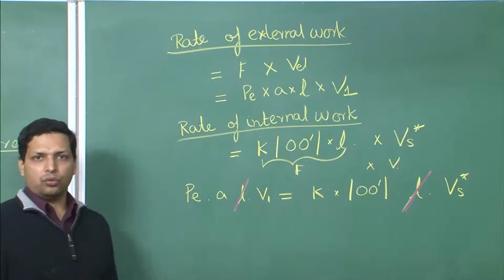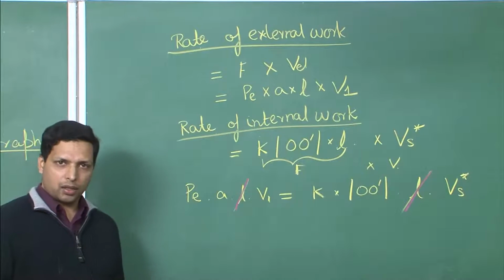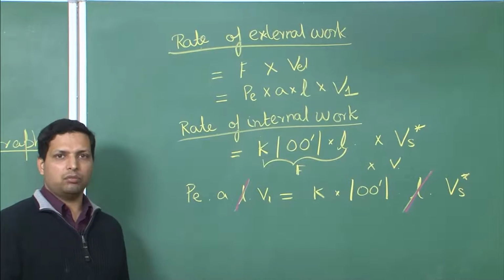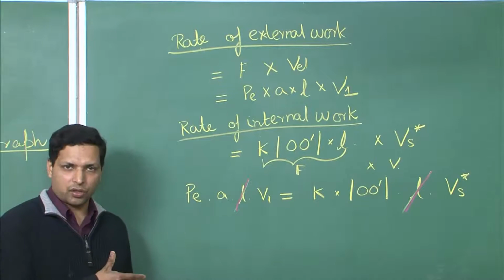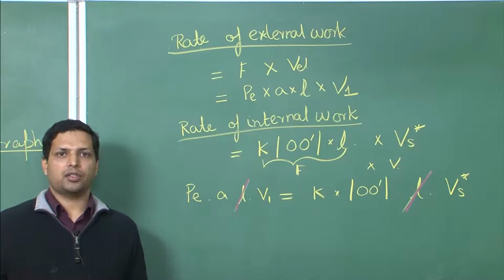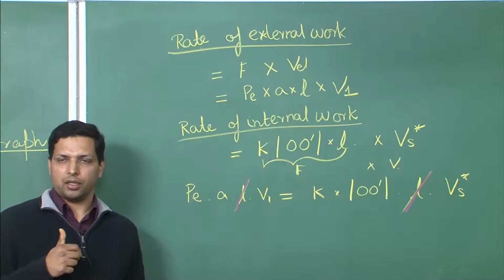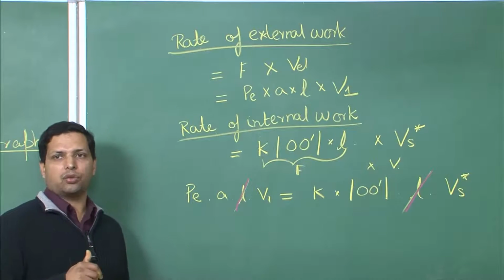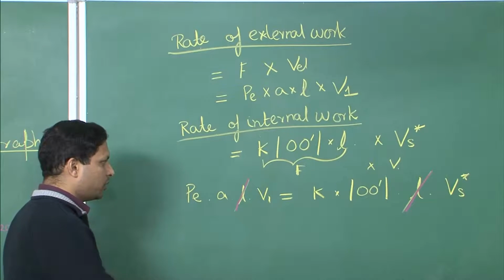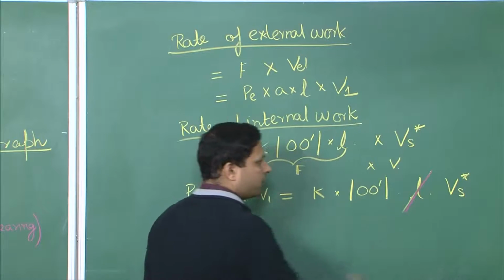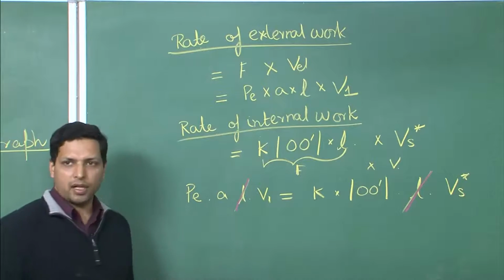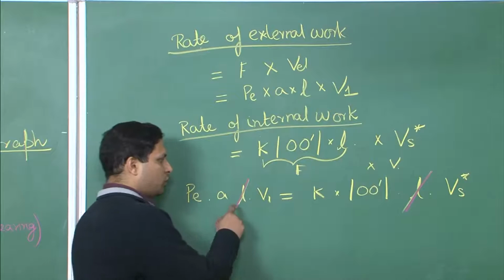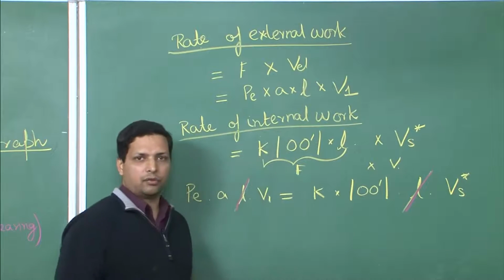and this will be true no matter what deformation field you assume, but you still make one assumption, which is that in the third direction or in the perpendicular direction the geometry remains constant, that is in the third direction there is no change in the geometry. So, as long as you take that, this L will always get cancelled, and because this will be true in general, we will not be showing this term in the future examples.